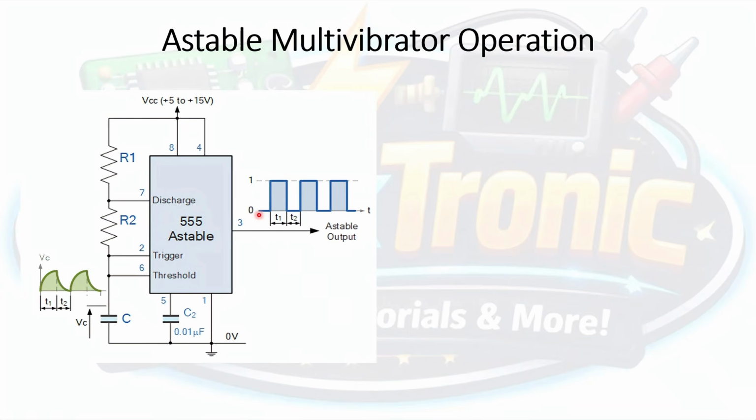So we have the square wave that will be pulsating from 0 to a high value. When the square wave is at 0, we expect the LED to be off. When the waveform is at this high value, we expect the LED to be on. How long the LED will be on and off depends on the value of R1, R2, and the capacitor. I'll show you the formula later on.